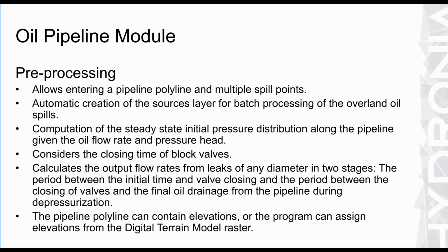The first stage is the period between the initial time, so the initial conditions in the pipeline, and the valve closing, and then the period between the closing of the valves and the final oil drainage from the pipeline during the depressurization. The pipeline polyline can contain elevations, or the program can assign the elevation based on the digital terrain model that you are using for the overland flow.